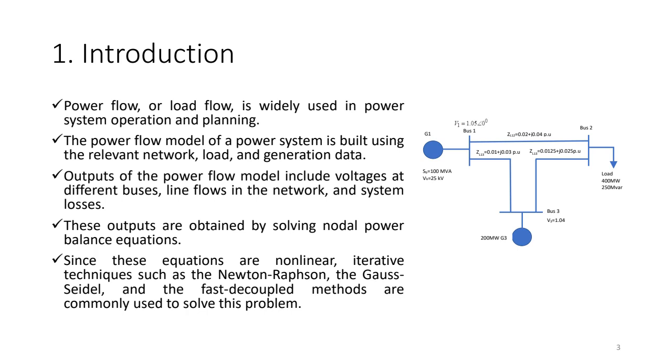As we spoke in the previous section, the load flow is used for understanding the operation and planning aspects of the power system. You can see there is a 3-bus power system given in the SLD diagram, and this is the exact network model that we modeled in the MATLAB simulation. Today we're also going to model this network in DIgSILENT and do the same load flow, and even compare the load flow results of MATLAB versus DIgSILENT.